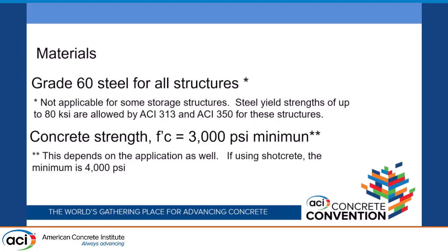So some of the things we look at during design are limitations on materials. The 318.2 and through the 334.1 document talks about grade 60 being the maximum that we can use for our steel. Okay, and there's an asterisk, and we'll talk about that. But the reason for that is because it's not a strength problem. Okay, so we don't want to use strength out to the very end, but we want to limit that tensile stress. We want to limit the cracking, even more than normal structures.